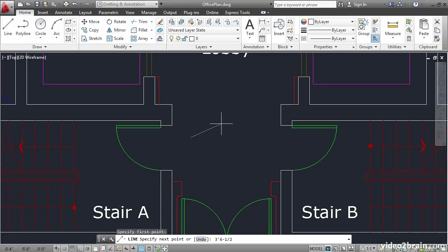The dash is necessary as a delimiter between the inches and the fractional inches. Without it, you'd either have 61 halves, or you'd have a space which would terminate this part of the command. Remember, the spacebar is equivalent to the Enter key. So the dash is necessary in imperial units when you're separating inches from fractions of an inch. So then I'll press Enter to specify that point. And now I've successfully drawn a line segment measuring this precise distance, 3 feet 6½ inches. I'll press Enter and then Enter again.